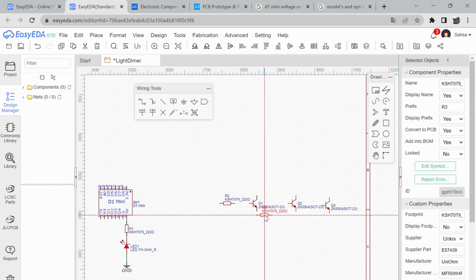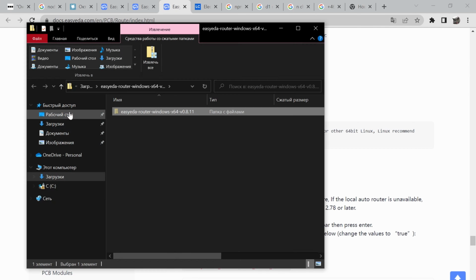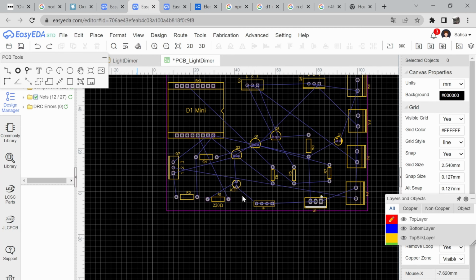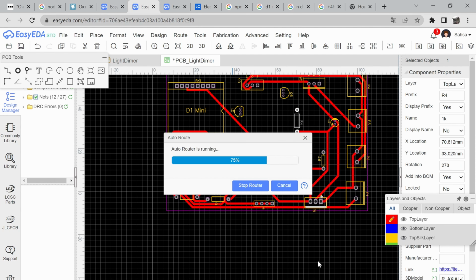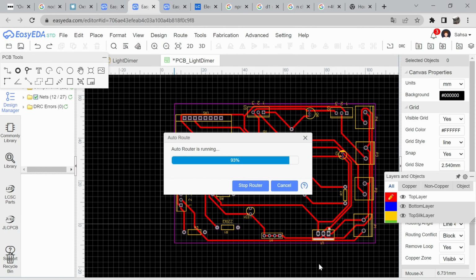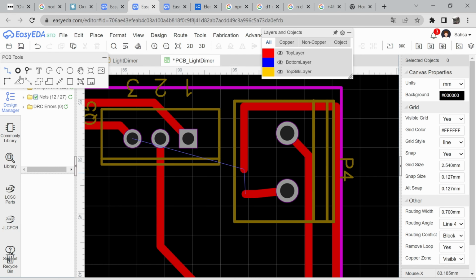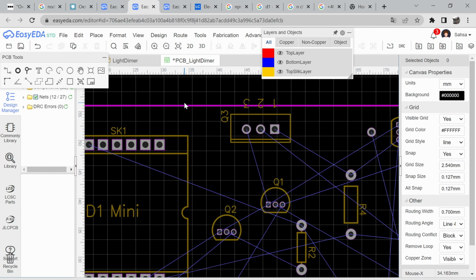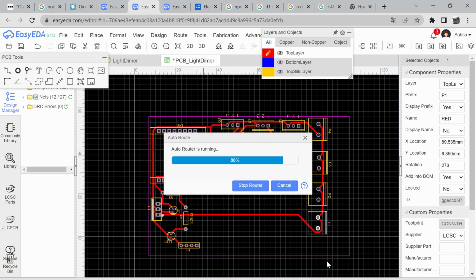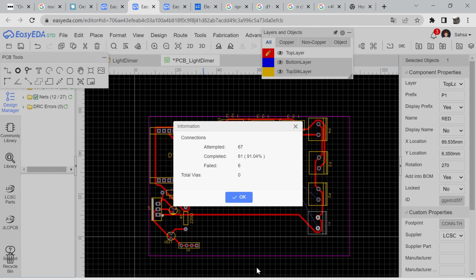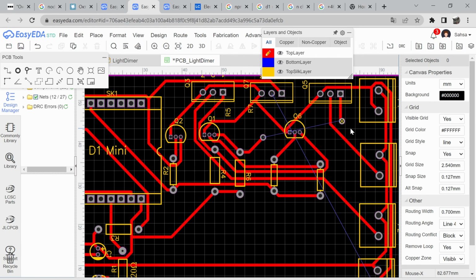The requirements for prototype 1 were simple: PCBs that can be made at university, ESP32 based, and it should drive one RGB LED strip that I already have, so it should be powered by 12 volts and not ask for another power source. So I started to make my first prototype.